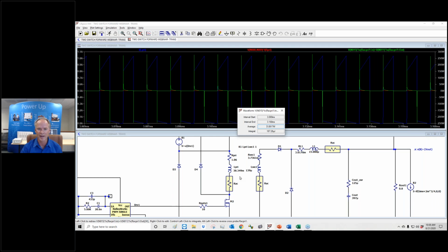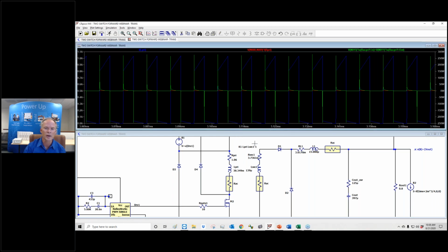If you add this 1.9 with the 0.3, I think it was, versus just the 0.3 watts of loss they expected, that's 7 times the loss in the transformer. And any of you who've been involved in power supply design for a long time, the one constant you know is that the transformer windings are always hotter than you think. And they will surprise you as the turns count goes up and your power levels go up.